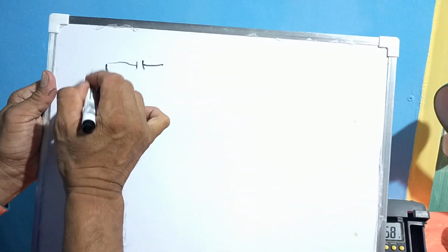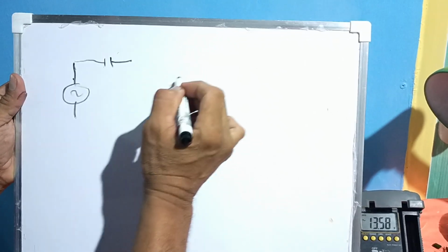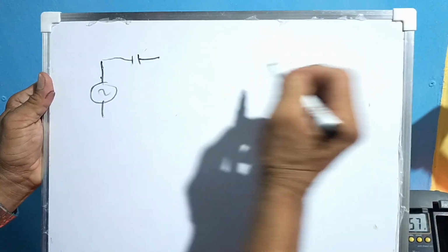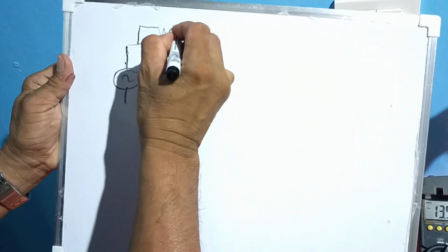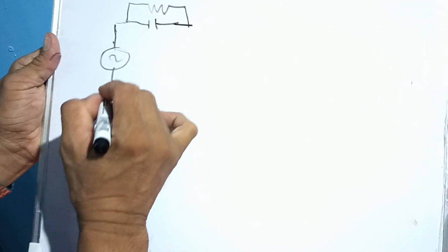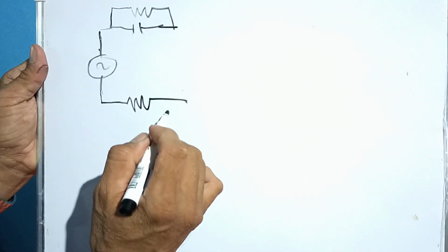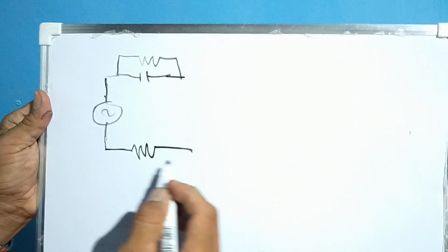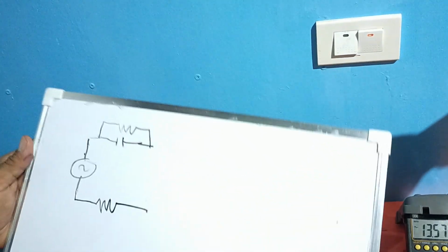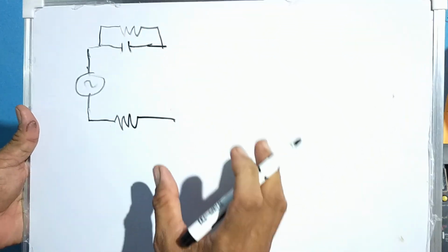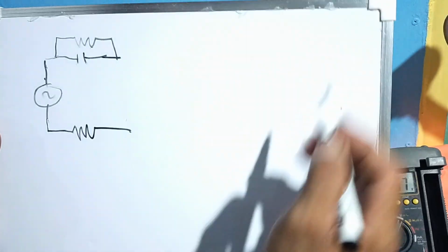If the voltage here is 230 volts, then this capacitor will drop an amount of voltage that will provide a desired lower amount of voltage at the output. It is actually paralleled with a resistor. Then the other line here is a resistor again that will limit the amount of current that will flow around the circuit. This is to prevent the harmonic distortion. We will explain in detail later on what this harmonic distortion caused by the circuit is.